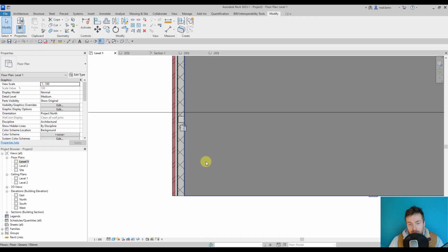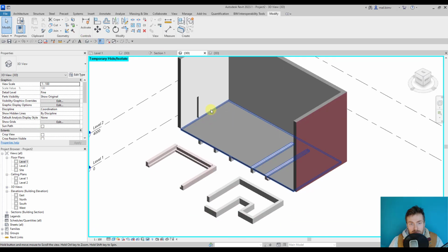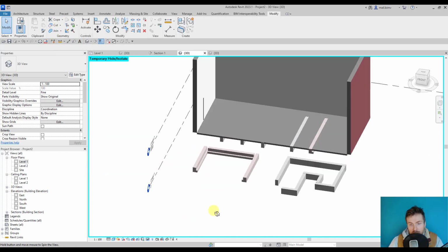So remember not to use the cut tool, but the join tool, as it may be counterintuitive to create a cutout using a join command, but this is how it works. And remember about the material behavior of elements, how it's deeply coded into the Revit environment.